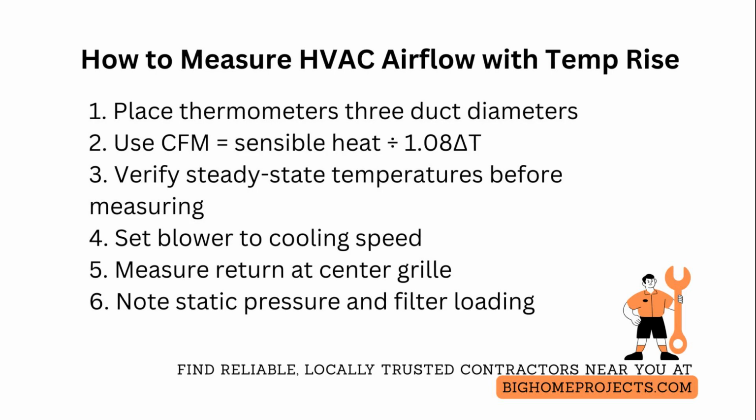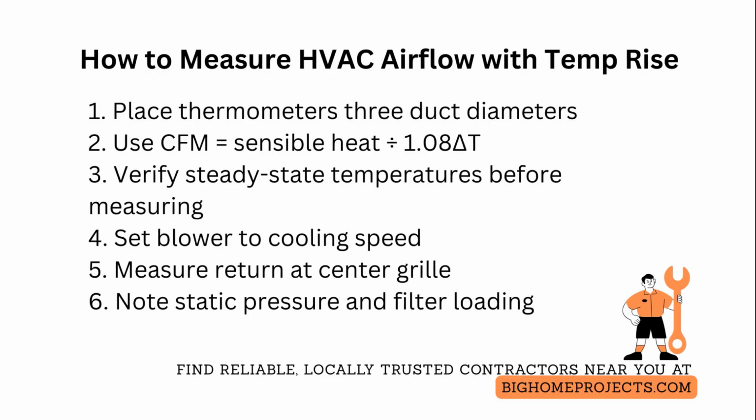Always run the furnace long enough to reach steady state, usually 20 to 30 minutes under normal ambient conditions, and log temperatures every minute to detect drift.